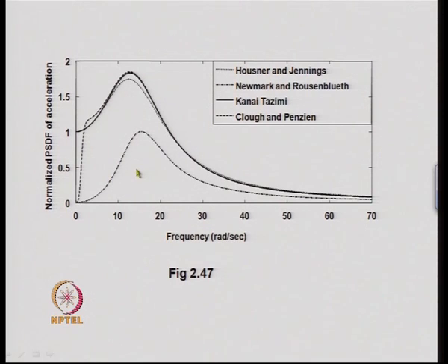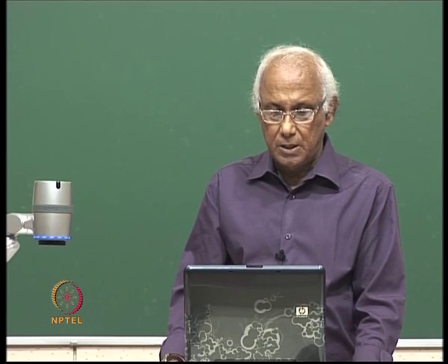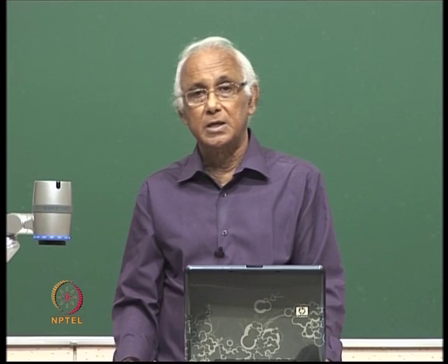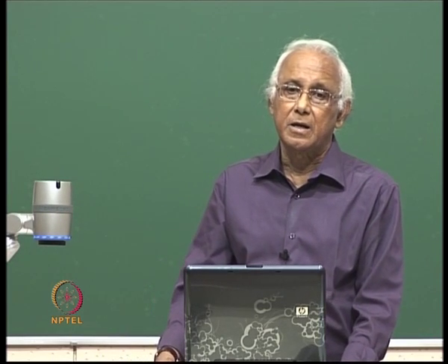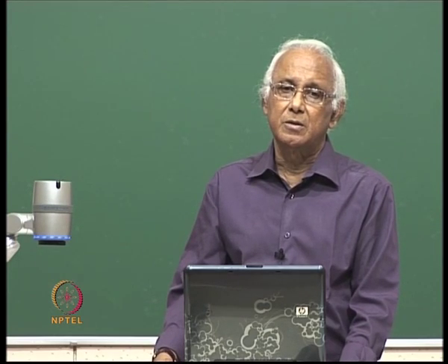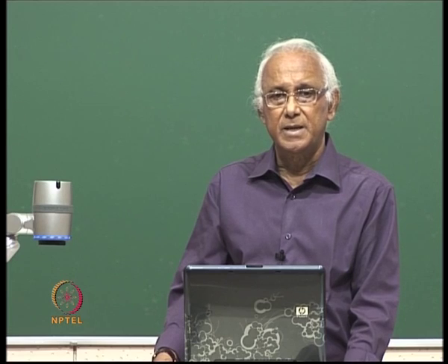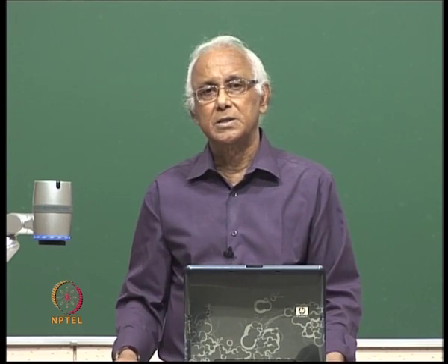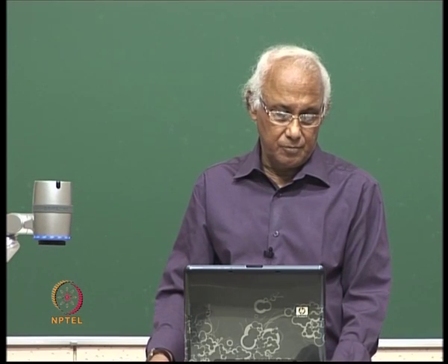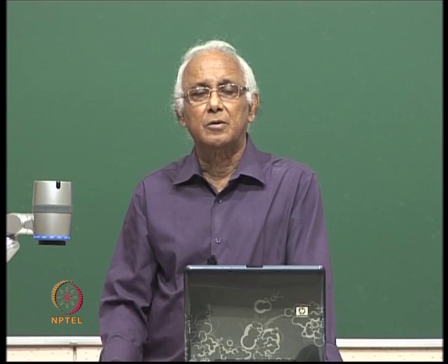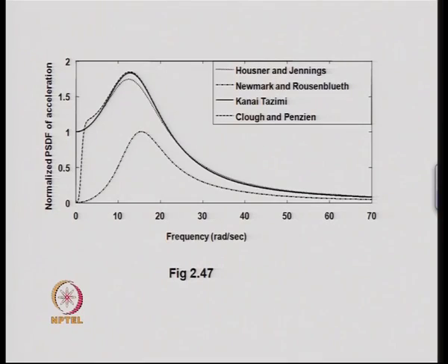So, this shows that we have different kinds of spectrums given by different equations, and which one is to be used depends upon the local condition, but the most widely used ones in the literature are found to match with most of the power spectral density functions obtained in the database, and therefore, the ones we generally accept for predicting the future earthquake can be taken from those equations.